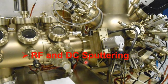This physical removal is usually done at a higher vacuum, though it's not an ultra high vacuum like molecular beam epitaxy. So this basically results in damage to the substrate surface and also the thin film. The thin film deposited with RF and DC sputtering is not uniform, and there is a possibility of a high level of impurity.